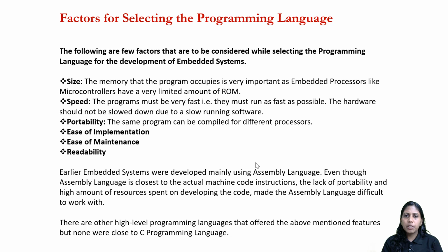The 8051 is an 8-bit machine, so the register size will be 8-bit, or 16-bit. The ARM controller is a 32-bit controller, so the instructions themselves will be different, the registers can be different, and the way we program can be different. That's why I'm saying assembly language is not portable. But on the other hand, whether you write the program in C, as we discussed already, the C program you are writing for host machines, right?